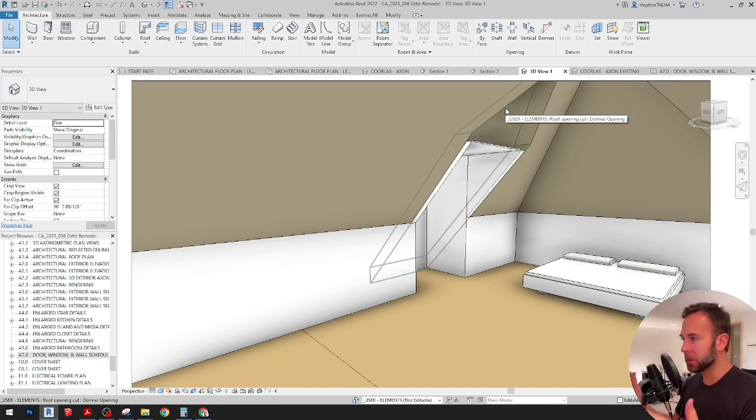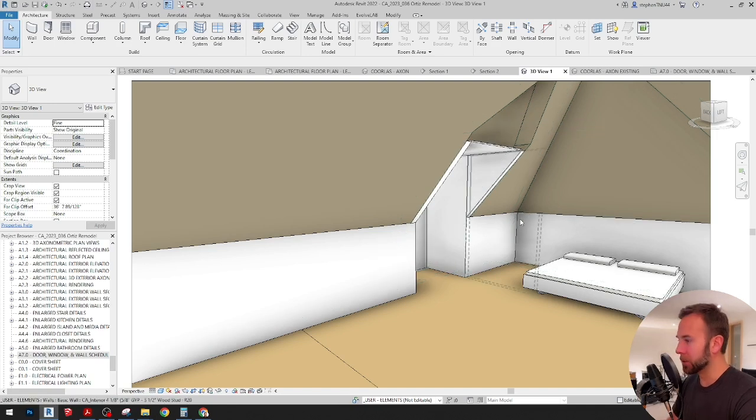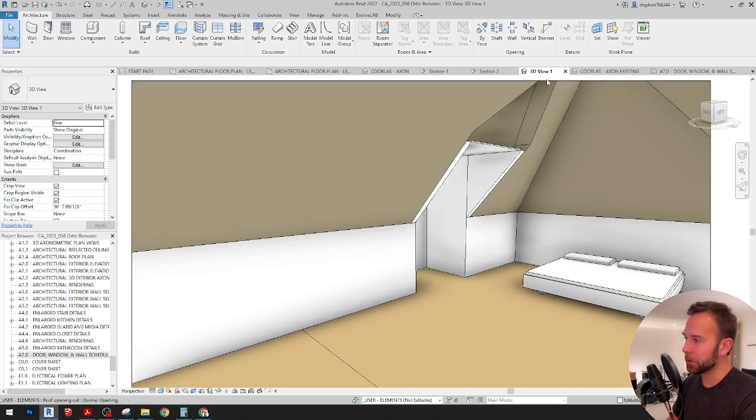And if we have a vaulted ceiling structure like this, you can tuck the lights up in between the rafter spaces and still get renderings to appear accurately so that the lights are not conflicting with the rafters, or in this case, the roof geometry, which is a solid. So anyway, that's sort of a detail, but we'll go ahead and model in with a generic model the ceiling plane, which will cover up some of this geometry.